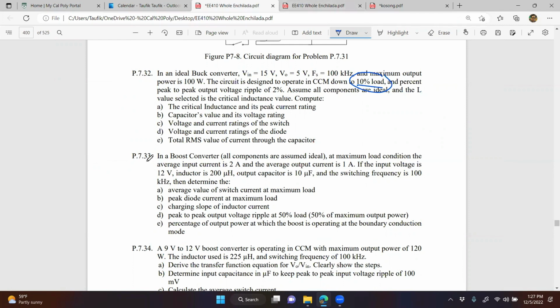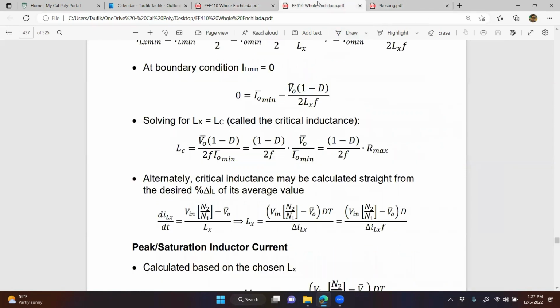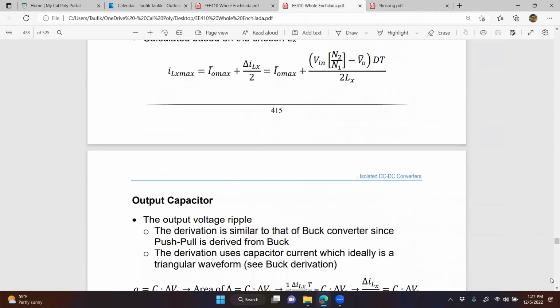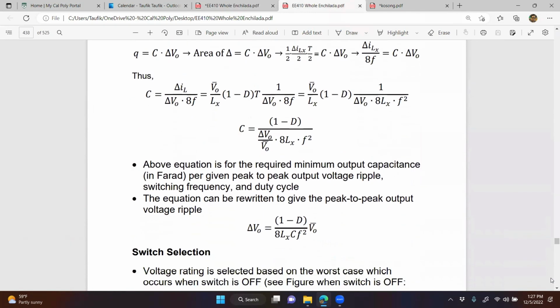So we don't have to do anything there, except when you give us the percent, the only thing we need in the equation is delta V out. We should multiply the percent by V out to get that delta. You could do that, but I thought the equation can also use delta V out over V out, which is already in percent.